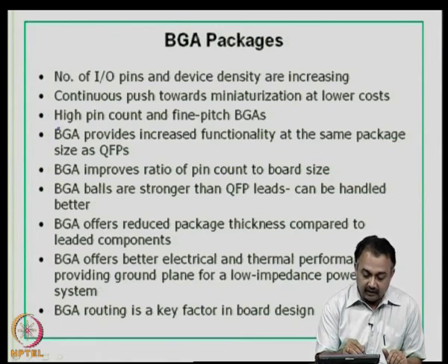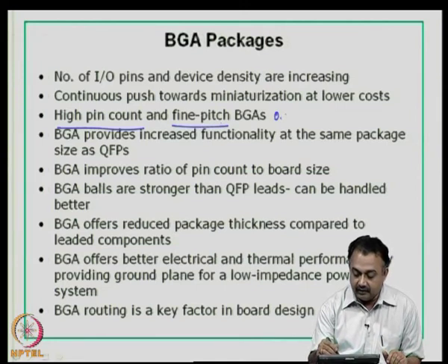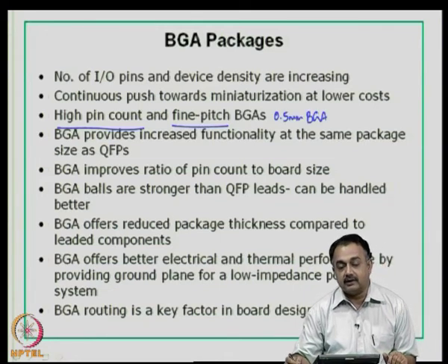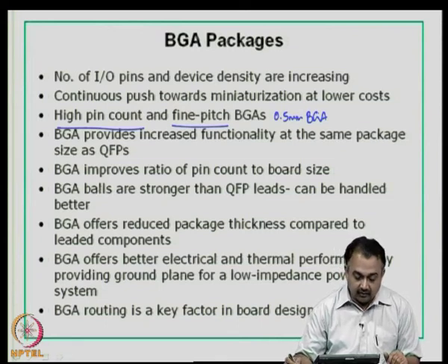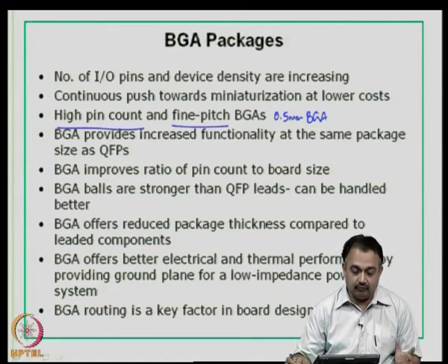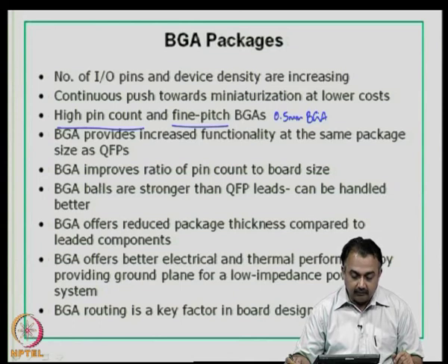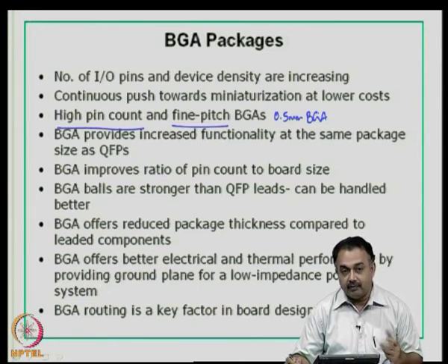So, it does not mean that you can have a high pin count, but large pitch, it has to be fine pitch. When I say fine pitch, we are talking about 0.5 mm BGAs. Below 0.5 mm, it is classified as a CSP. BGA provides increased functionality at the same package size as QFPs because of these two factors, fine pitch and multi-layer buildup. BGA improves ratio of pin count to board size, again because of fine pitch,